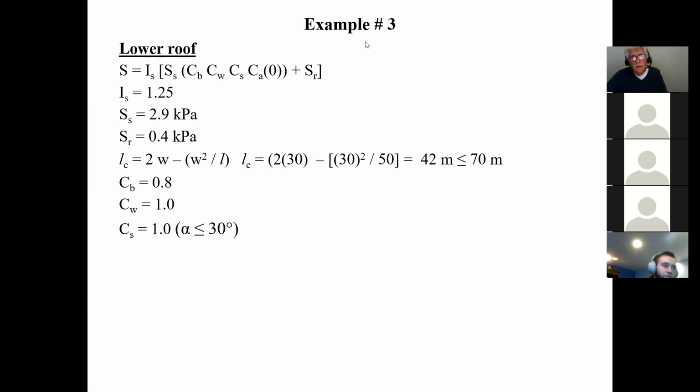So what we're saying is that here's the upper roof, here's the lower roof, okay? I know that I'm going to end up with some kind of load that looks like this. Here, believe it or not, is the same value as here because I just want to be able to calculate what's the value right there. In other words, where X is equal to 0, okay? That's what they mean by XO. How much of a load do I have there? And that's what this factor does. It gives me the value that I have to put in an equation to calculate the value right there.